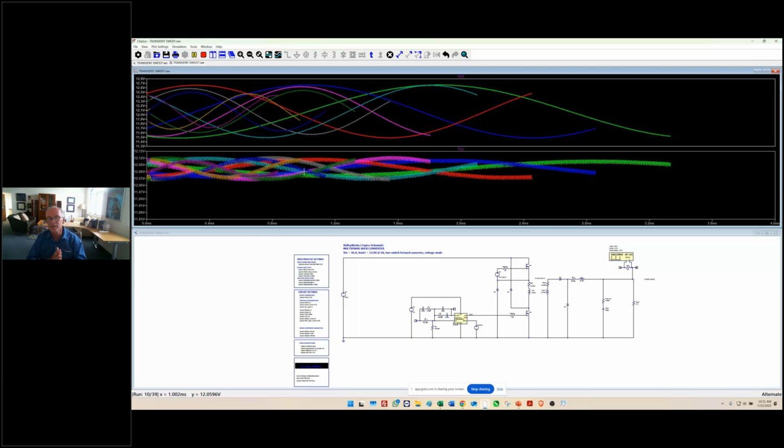I know LTspice builds in its own frequency response analyzer now, but it doesn't do what we do, which is showing you both of these signals, which gives you intuitive insight into how a frequency response analyzer works in the real world. So I do encourage you to try this. And you can see we've done 24 runs out of 39. The speed of this, yeah, some people get upset, well, that's too slow. It's like, well, this is way, way faster than you having to generate a small signal model or having to go find those equations, which may not exist, which means you have to go derive those equations.